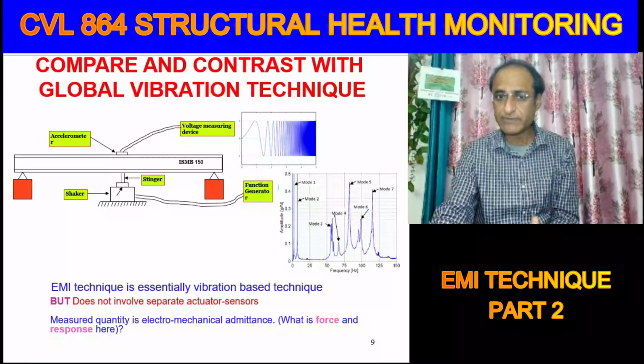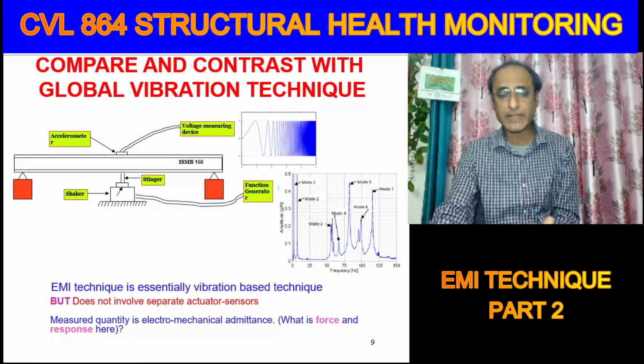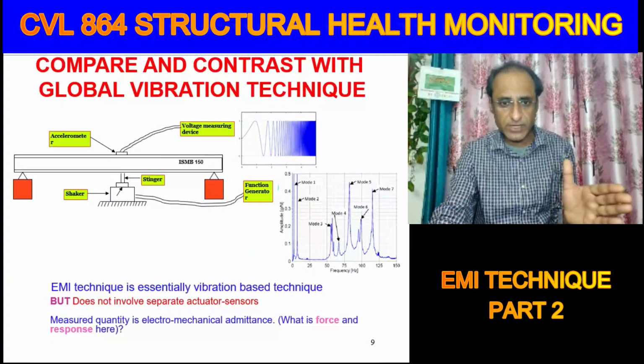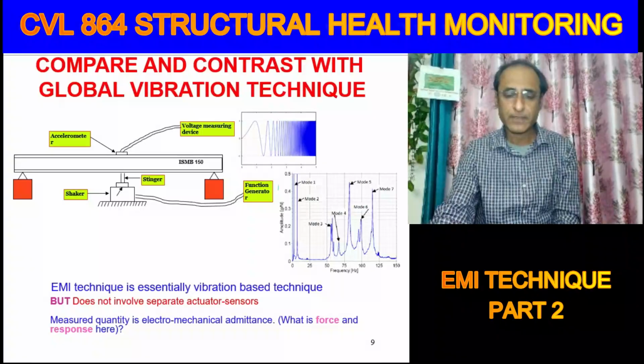The piezo itself will act as the shaker and apply sinusoidal voltage. We are applying sinusoidal voltage across the piezo, and this will actuate the structure into harmonic vibrations, and we are gradually changing the frequency, so it's a sweep kind of vibration pattern.